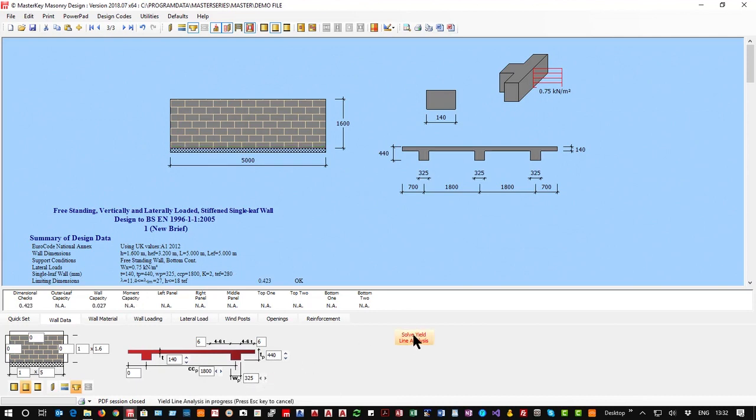And try that. But what I can also do is I can say, well, how close together do they need to be? And at 1500, they're just 3% overstressed. So I would need these piers quite close together.